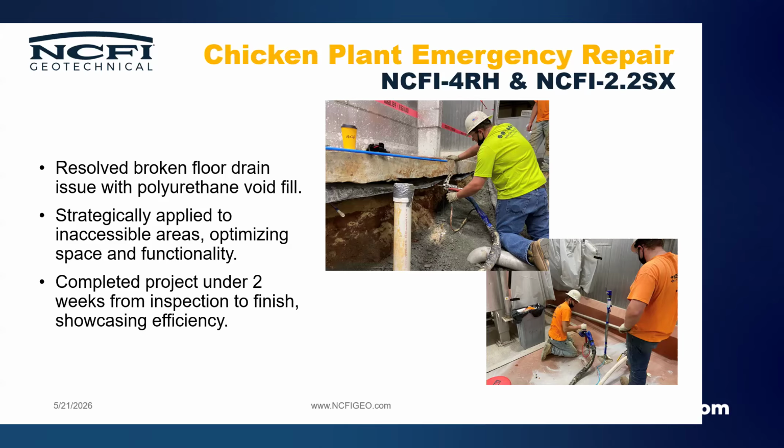And then anywhere they didn't take out the slab, we did void fills just to make sure that everything was filled in. So we just basically void filled until we got a bump on our level. We also went through, and all these PVC pipes that they didn't have access to tear out, we abandoned those with the 2.2 SX, filling those in just to keep them from being an issue down the road.